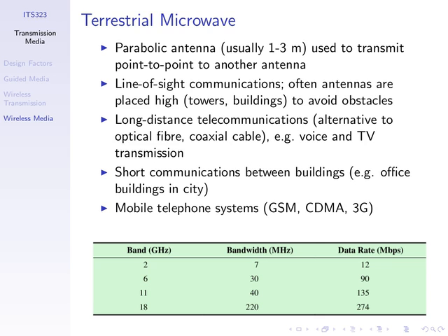The difference between the maximum and minimum frequency component is 10 megahertz, if I've got my math correct. So in practical situations we often talk about the frequency of the signal, which is just the frequency of one component, or the center frequency, say 2 gigahertz, and the bandwidth of that signal. So the band column here is referring to the frequency band, say the center frequency.